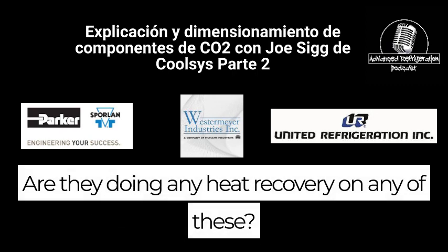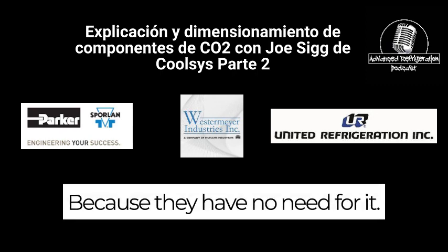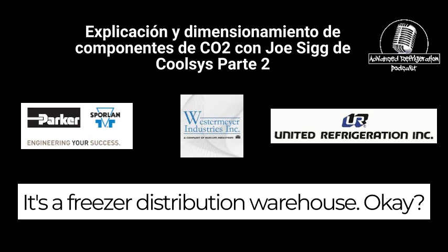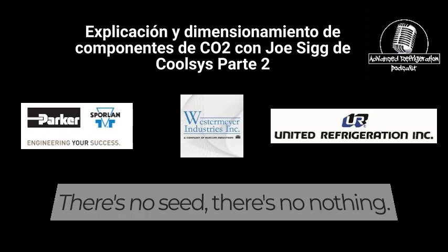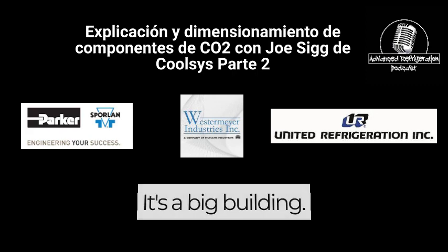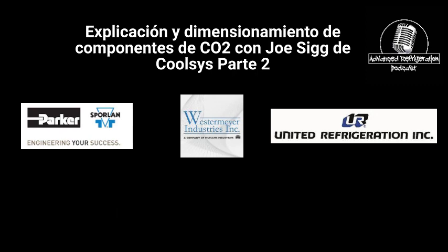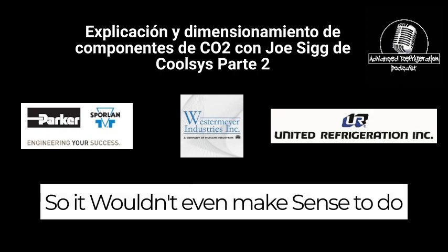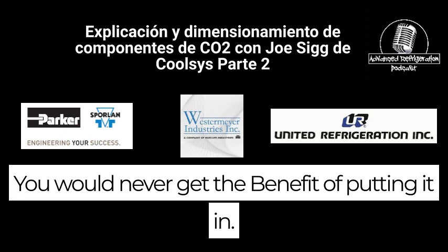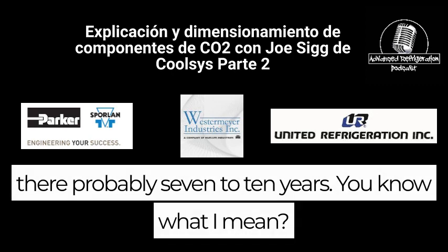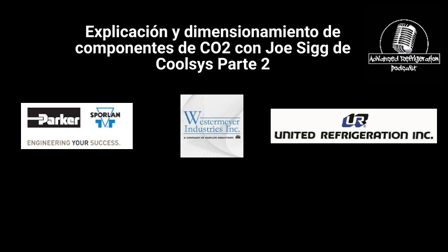Are they doing any heat recovery on any of these? No. Why? Because they have no need for it. It's a freezer distribution warehouse, so it's not like a process. There's no hot water, no AC, nothing. It's a big building that's basically a walk-in box, with some offices in the front. So it wouldn't even make sense to do heat reclaim. You would never get the benefit of putting it in. The ROI would be way out there, probably 7 to 10 years. Once you're done installing it, who cares, right?